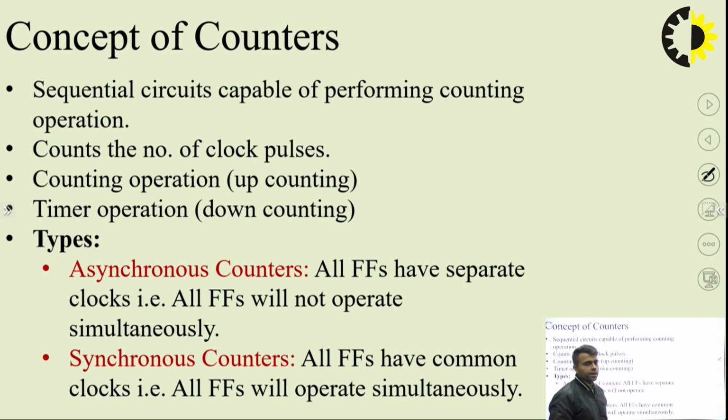So concept of counters. What are counters? If I'm designing a counter, it will be counting, but what will it be counting? It will be counting the number of clock pulses that will be entering the circuit. We are very much aware that counters will be made of flip-flops, and flip-flops cannot work in absence of clock. So the number of clock pulses that will be entering that structure of flip-flops, which is termed as counter, will be counted and displayed in binary format at the flip-flops output. So this is counter.